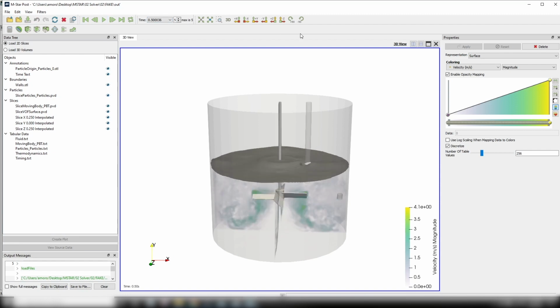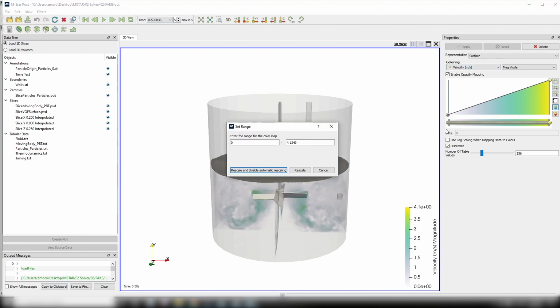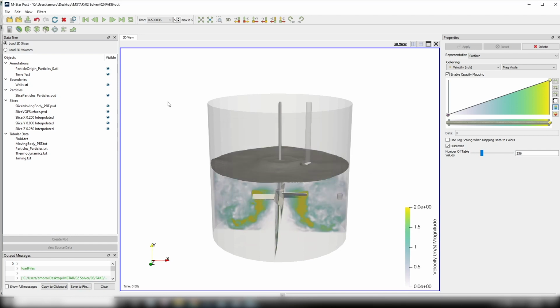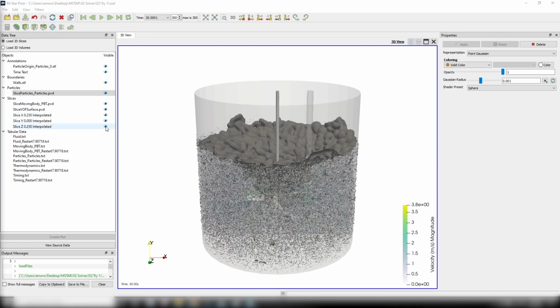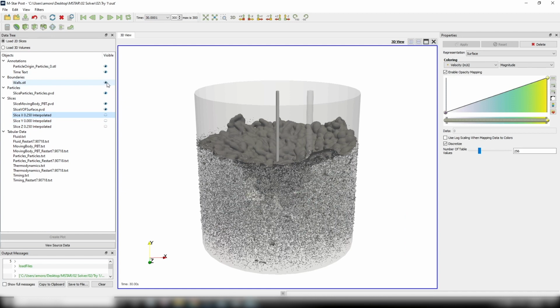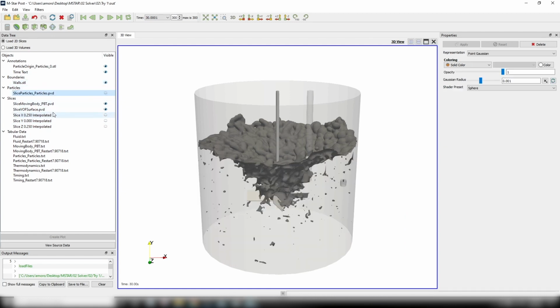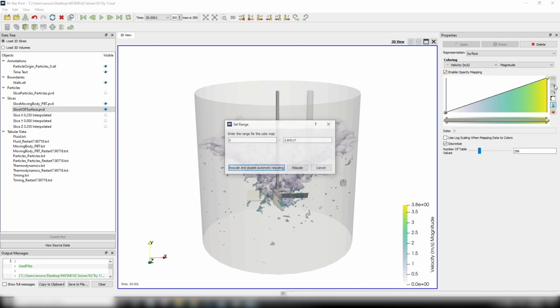Here we can see the position of the interface, as well as the fluid moving along the output planes. If we change the color scale on the planes from 0 to 2 meters per second, we can let the code run and see the fluid move. After the code is run to completion, we can refresh all the data, turn off the planes, and render the free surface by velocity going from 0 to 0.5 meters per second.